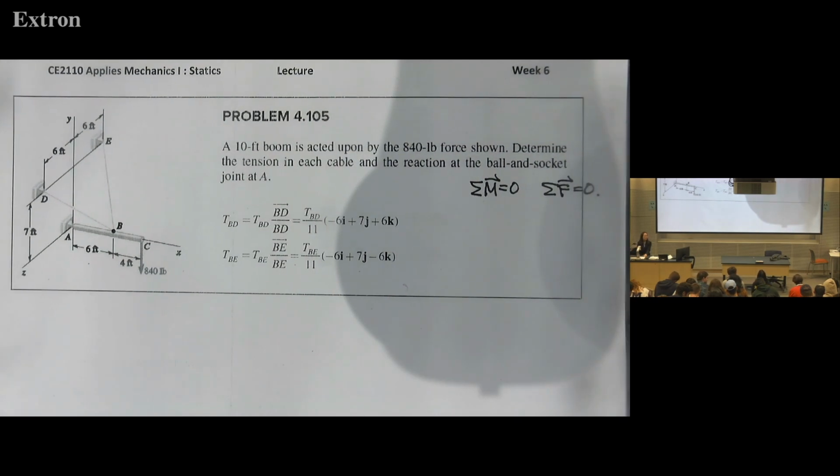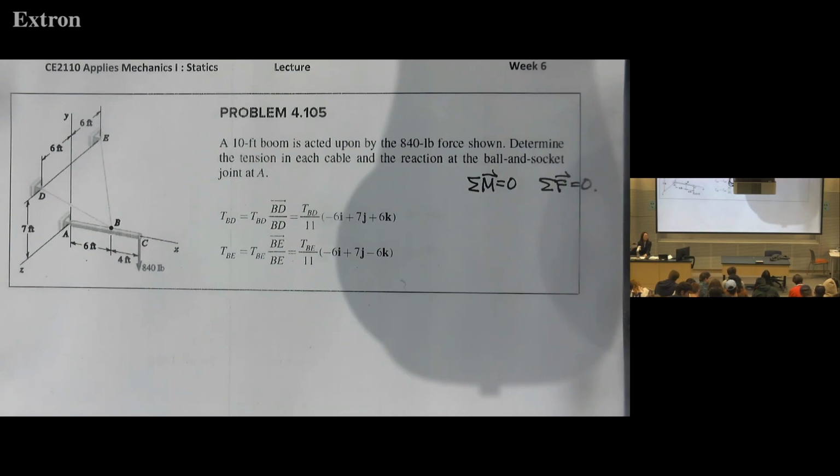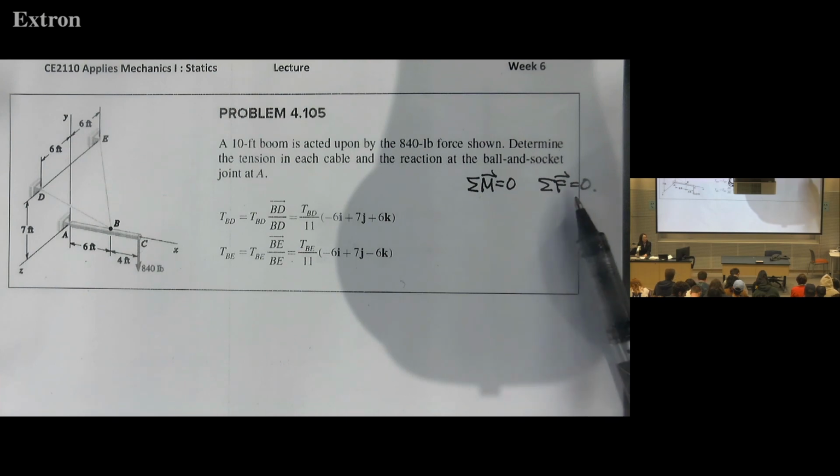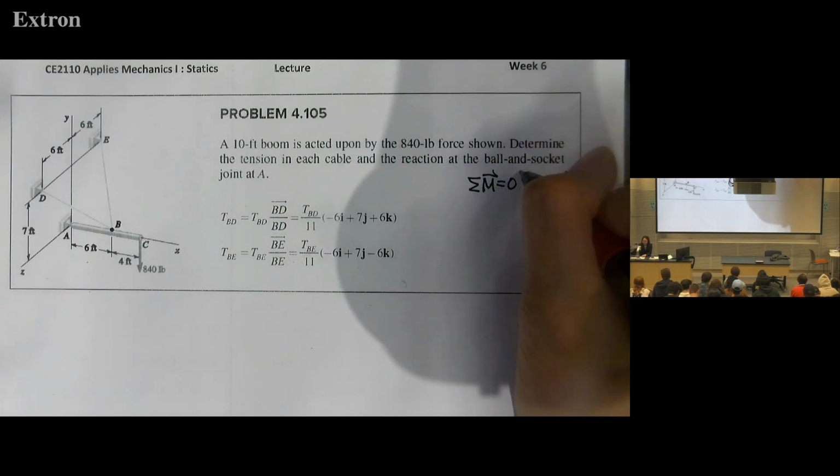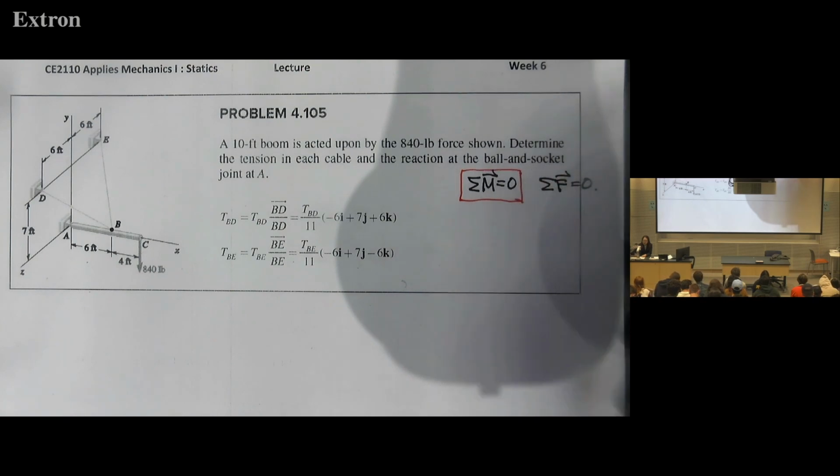Sum of, so sigma moment vector in the system, and then sum of all the force should be 0, right? So these 2 equations are what we'll solve today here. And then like 2D, always start with moment equilibrium equations first. Then we will solve some unknown reactions, and then move on to force equilibrium equation to find the remainder of unknowns.